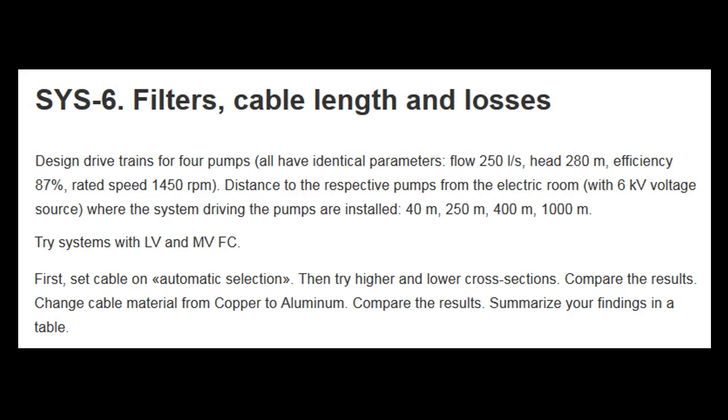So here you are to choose the right topology and the right voltage level for your electric machine and frequency converter, and you can play with that because you can use a transformer with different ratio. So you can have, for example, a 3.3 kV solution, or you can have 400 volts and 690 volts in your system. And here you should be careful with what type of transformer and frequency converter, and filters between the frequency converter and the electric machine you have.